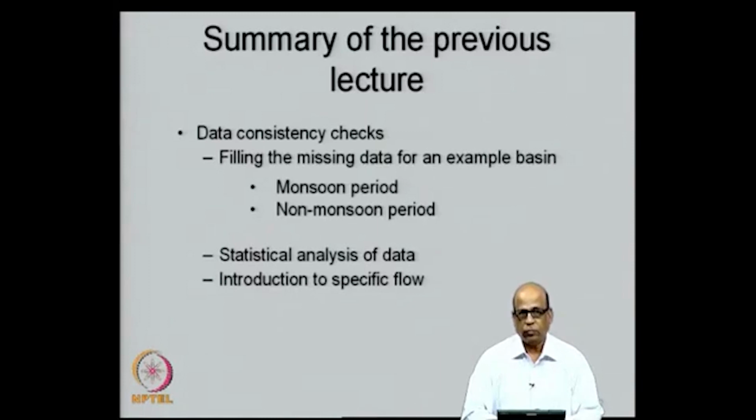Typically, whenever we have hydrologic time series, especially in developing countries like ours, we may not have continuous records. There may be certain values that are missing, and it is important for our analysis to have a continuous time series of data, and therefore, we adopt the procedures that I discussed for filling of the missing data.